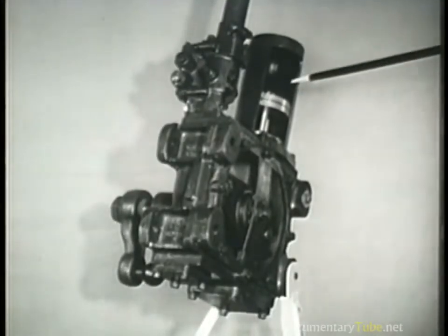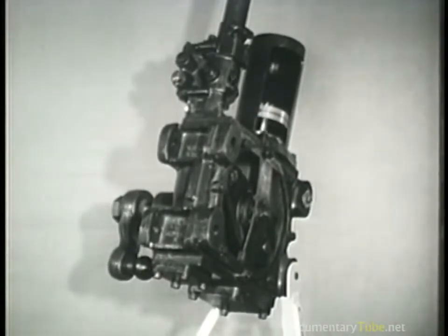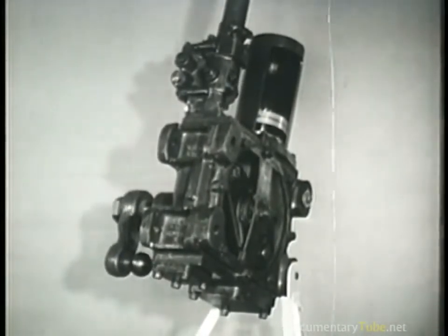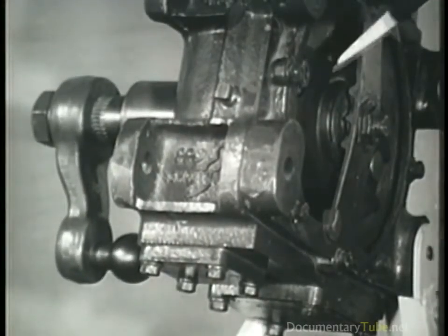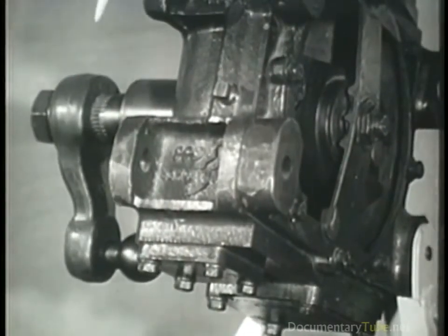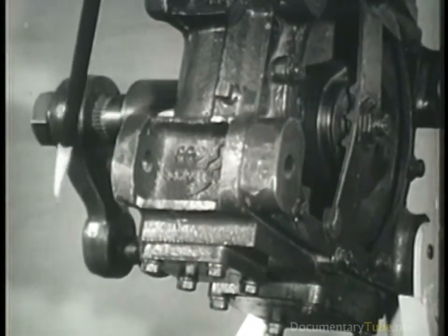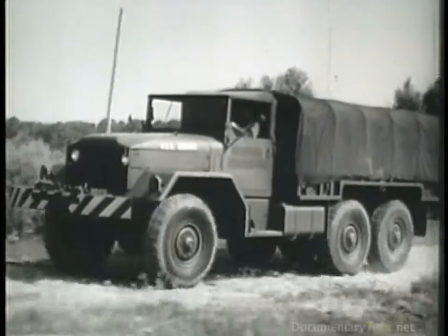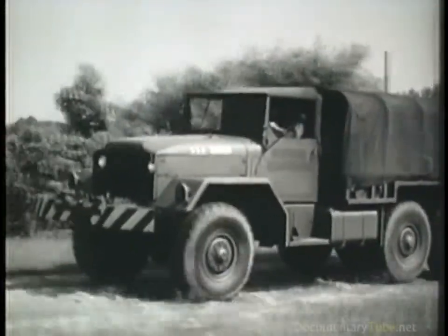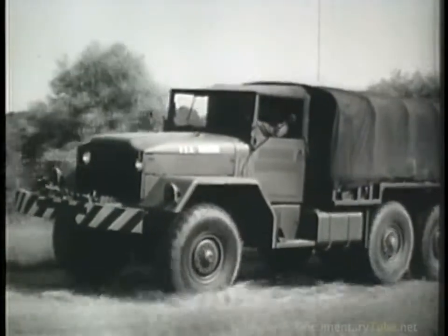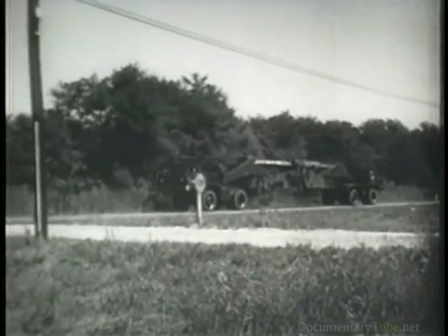The slightest movement of the cam results in a pressure differential in the power cylinder and an applied force on the pitman arm shaft and lever and the pitman arm. The hydraulic steering system resists shock and kickback through a reverse action in the power cylinder. With military vehicles getting larger and heavier